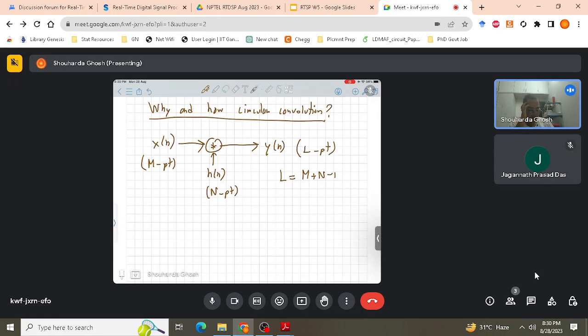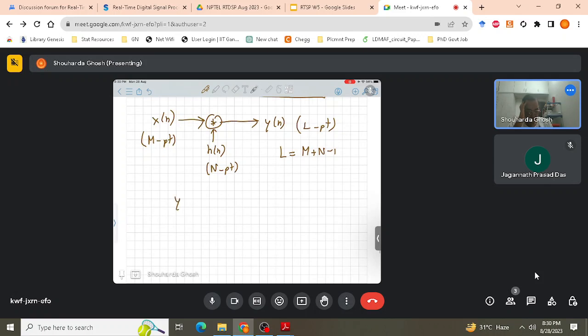Now this convolution, let's say y[n], equals summation of x[k] h[n minus k], where k is summed from a certain limit to a certain limit, n1 to n2, depending on how the signals are placed. So you are doing these multiplications followed by additions for all values of n, which is a lot of multiplications and additions.